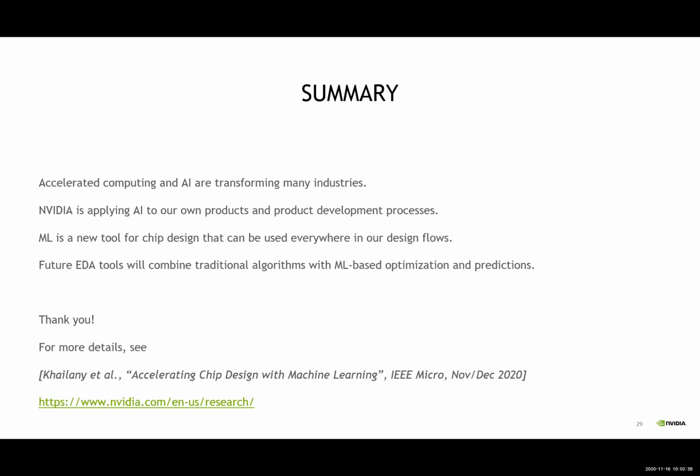Once you create that, it's no longer a hypergraph anymore, because now you can explicitly describe the hyperedge, which is basically a point-to-point node-to-node edge between the device node and the net nodes, right? So that basically decomposes the problem. There's no hypergraph anymore. It becomes just a simple graph, and you work on the heterogeneous graph. So that's the way we propose to do it.